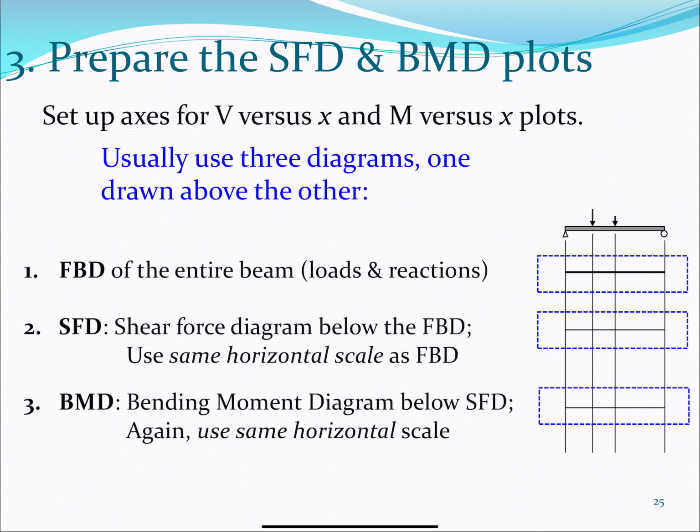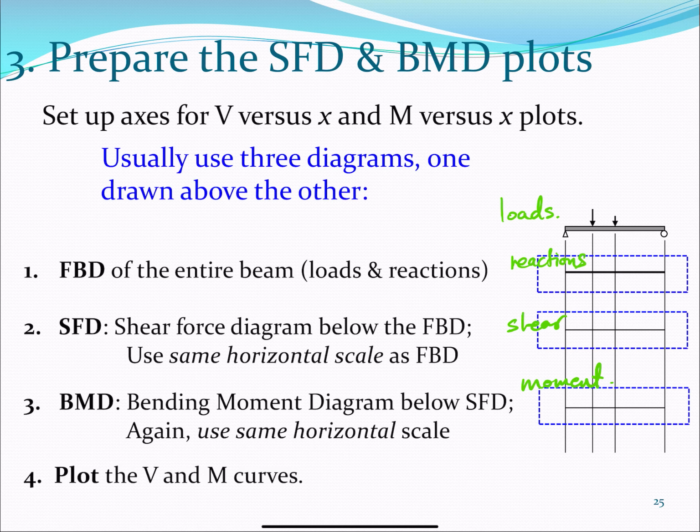So we can take a look at loads and geometry on top, and then reactions here, and then shear here, and then moment in this diagram, right? So using neat drawings, we plot these diagrams one below the other, and we plot, of course, our functions.